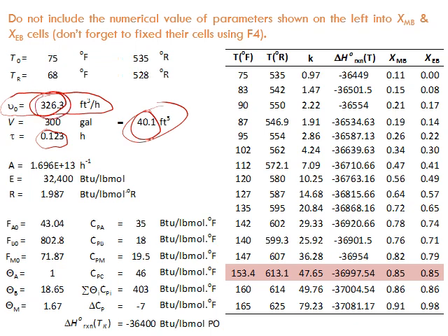Then we entered the value of the Arrhenius constant, the value of E, and R. Actually, even these values you can avoid entering by using the respective volumetric flow rate, the respective density, and the respective molar mass. You can do this, and then automatically I calculate the thetas. So these are not entered; these are linked to theta, this F and that F.